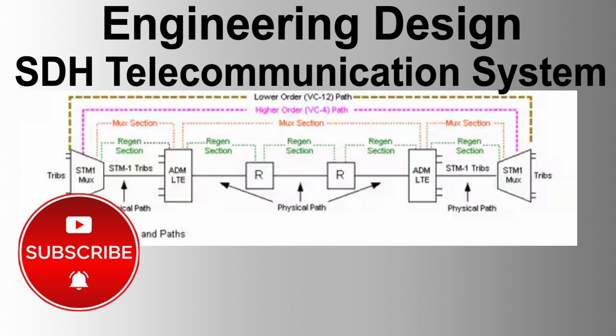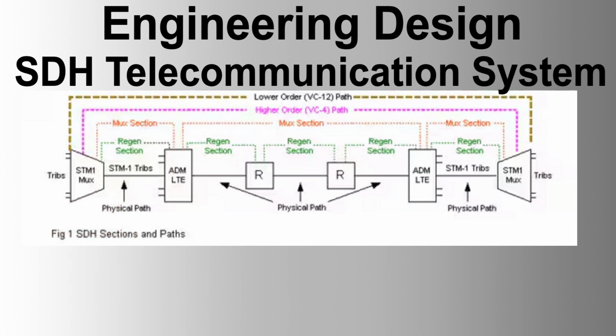EOW service channels. Engineer order wire, EOW. EOW shall be provided for each OLT to enable communications between nodes during maintenance and commissioning periods. It should be directly modulated onto the aggregate optical line signal.